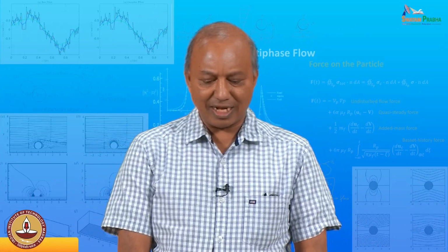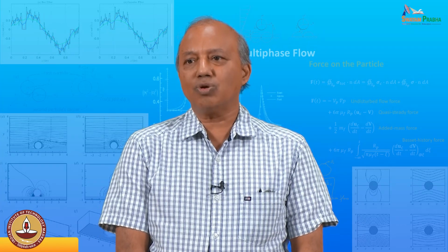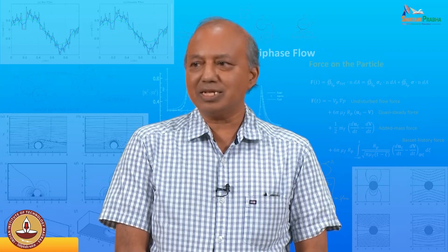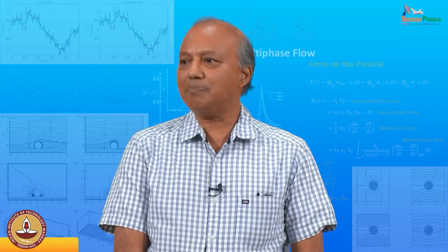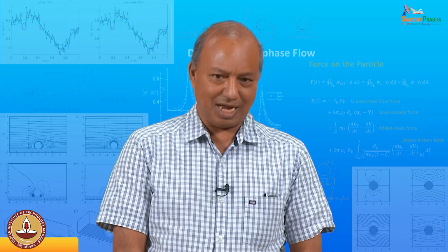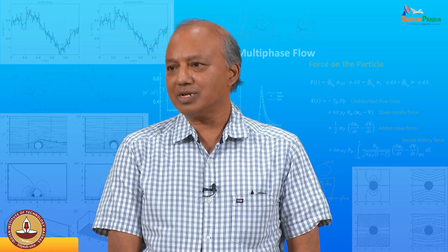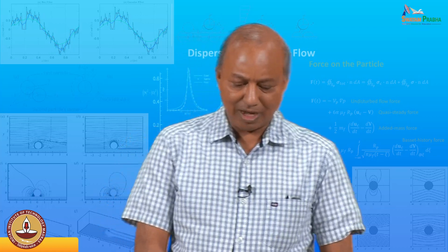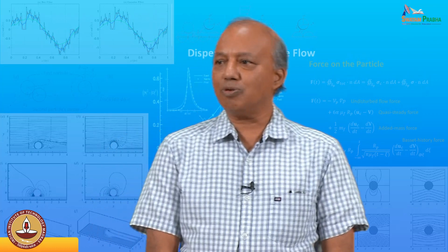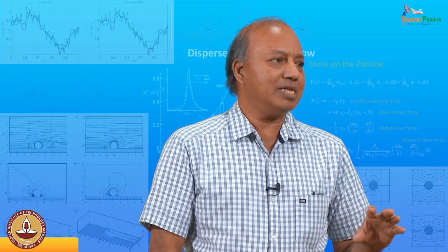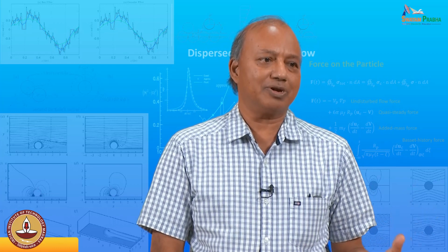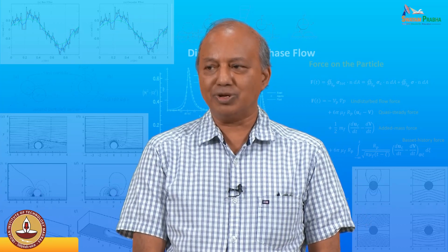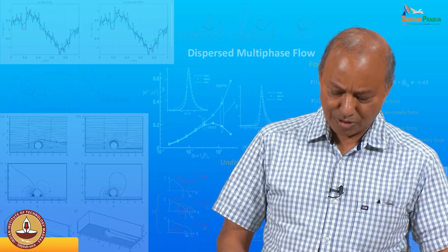Again, I want to emphasize the point that ensemble average will have all the symmetries of the problem. In other words, if you are dealing with a nominally steady flow, even though the flow itself is time dependent, if the statistics are time independent, then ensemble average equations will become steady, whereas volume average will not have that symmetry. And the same thing about spatial symmetries, whether your problem is homogeneous in certain directions, only the ensemble average will preserve the underlying symmetries of the problem, whereas you have to solve a 3D time dependent problem when you just coarse grain it, or when you use volume average approach.